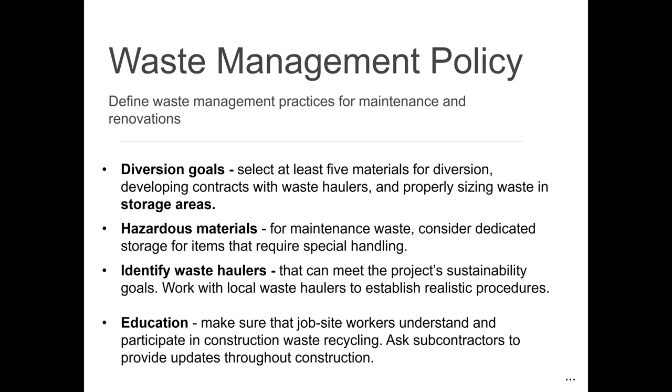Hazardous materials, for any type of maintenance waste, you want to look at dedicated storage for items that require special handling. So any types of batteries or lamps sometimes have those special handling storage cases. Identify your waste haulers and ask them what reports they can provide, what their typical practices are in terms of hauling waste and recycling rates. Those are always some good questions to ask them. And then lastly, education, making sure that job site workers understand and can participate in that construction waste recycling.